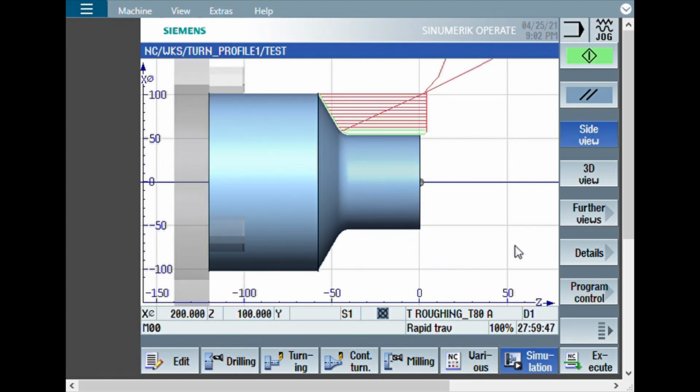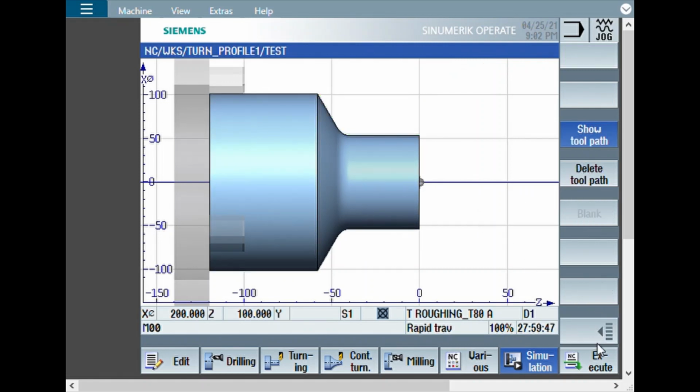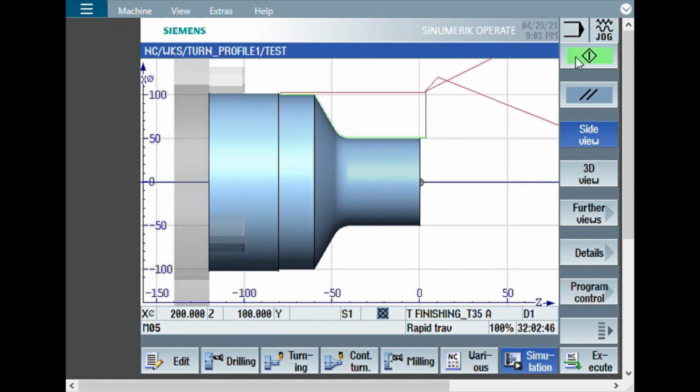Then we'll use the same delete toolpath option. Now we'll see it will appear as 2 mm directly removed. That is okay. Just for simulation purpose we are doing it. When you are actually doing, you need to control the depth. You need to keep only whatever allowance is required, say 0.15, 0.5 like that.